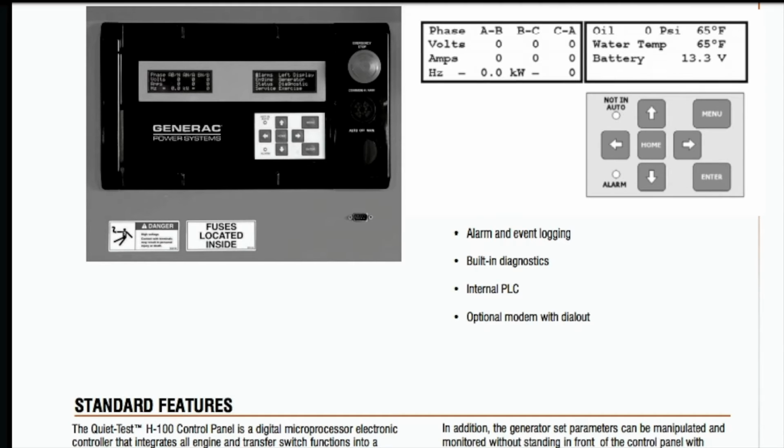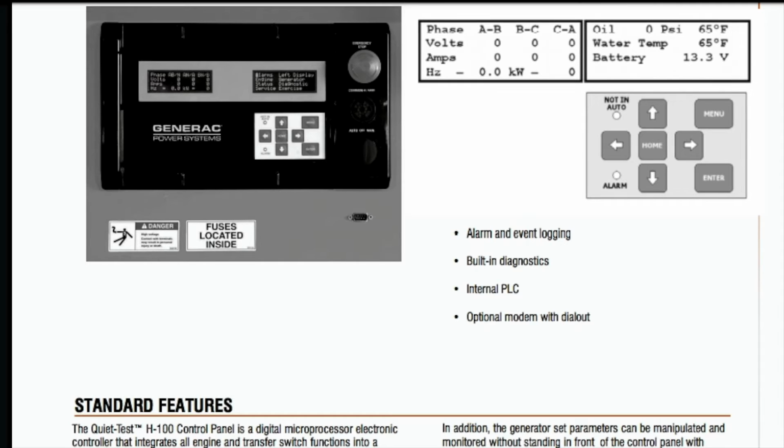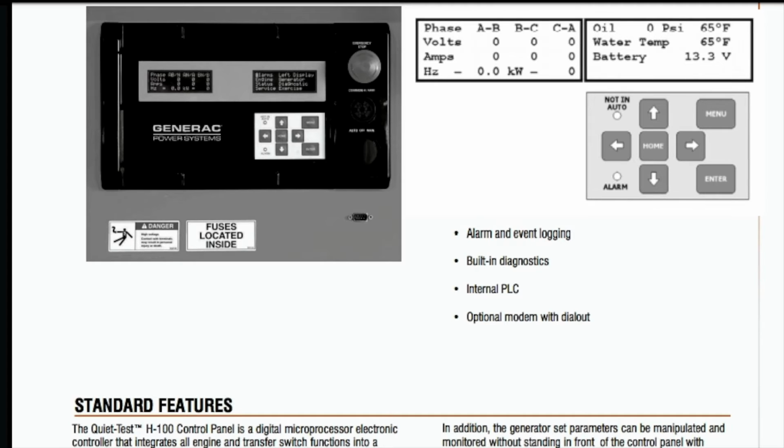So we can see an example of that right display there. There are several pages on here. It responds directly to the keypad. There are 2 quick buttons on the keypad that are used to go directly to either the home page or the menu page. The enter button is used to enter and exit edit mode, operate in output override, or select another page.